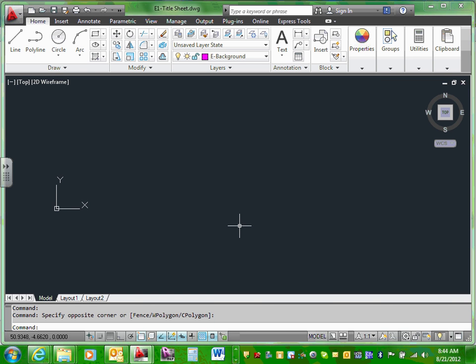Okay? Now, what does Xref mean? Xref means go get an image from what the architects have decided to do and work on this image. Why do we do Xref? Anybody knows why? Xref means you are looking at a copy from the architects. The power of Xref is when the architects change their mind, you will be able to see it. You're not working in the image, you're looking at the image. So if the architects went and changed the file that we're going to Xref here, every time you open your drawings or load it or save it, you'll be able to see all their changes.